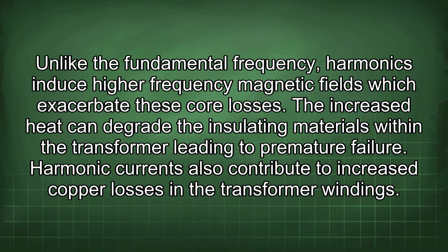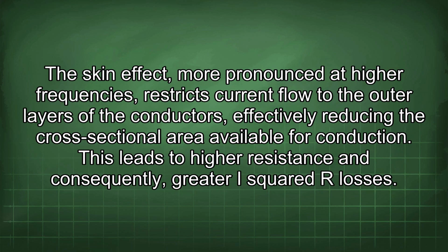Harmonic currents also contribute to increased copper losses in the transformer windings. The skin effect, more pronounced at higher frequencies, restricts current flow to the outer layers of the conductors, effectively reducing the cross-sectional area available for conduction. This leads to higher resistance and consequently greater I²R losses.